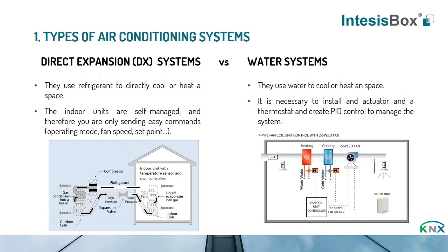Also, I have to say that in order to control water systems, as also Christoph explained before in his presentation, you need to install some additional devices. For example, a room unit, a thermostat, to control the temperature of the room and to create the PID control. And you need also an additional controller that can regulate, open and close the valves and switch off or switch on the different fan speeds.